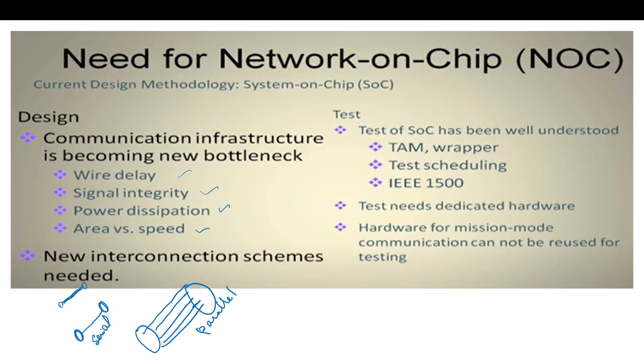If we are using faster communication, with high speed, we are able to transfer data at high speed because, say we have 5 buses running in parallel, then we can transmit 5 bits at a time. Here only one is possible, but here there is an issue of crosstalk. So we have that model of aggressor.